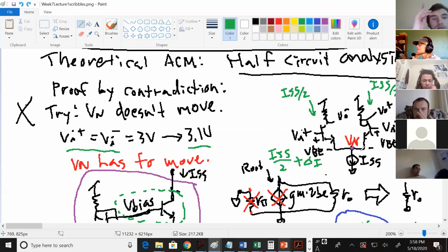Make it cascoded instead of having a passive load. Okay, yes, so you cascode both the Vn plus and the Vn minus transistor, and you replace these resistors with cascodes. What's in between cascoded and passive load? An active load. Okay, so you've got this passive load. This is the lowest gain. Then you could replace it with an active load. That increases the gain. You can cascode everything.